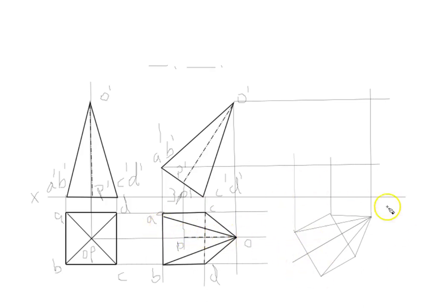You can start anywhere in this area. You can start drawing a line like this, and simply on your divider, when you draw manually, you take these distances of points A, B, C and D and mark them with respect to this axis perpendicularly, since all these points lie perpendicular to this axis. Suppose we mark this point as the axis, and from there you draw lines to this point.